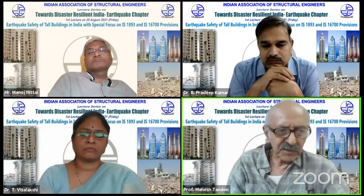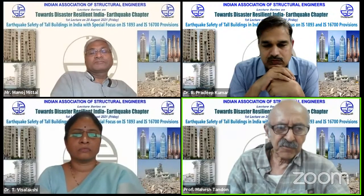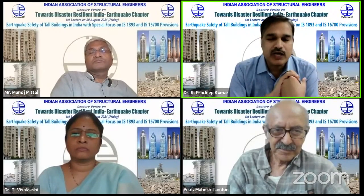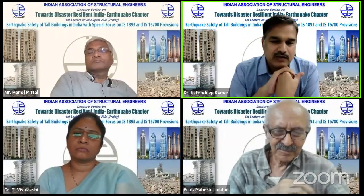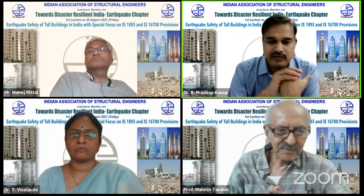Again, Mr. Sushil Dhawan. First question: how to take the effect of vibrations due to wind for upper floors in tall buildings? We need to calculate the wind force, and if the building height is more than 150 meters, it is better to do wind tunnel tests, like site-specific studies for earthquake. So then we get a force from that.